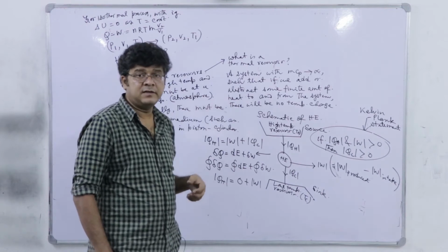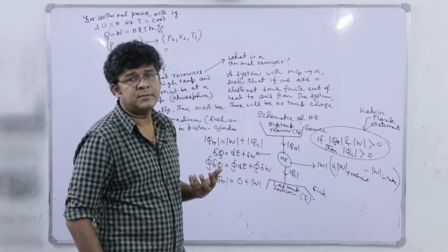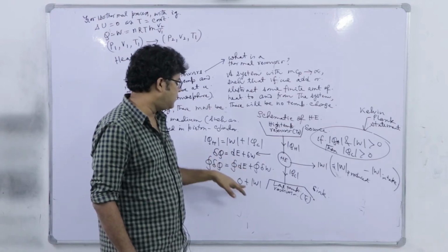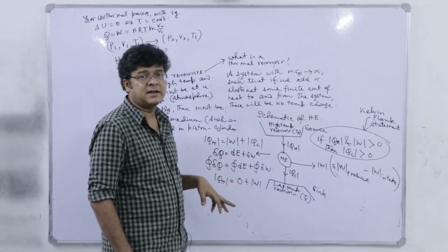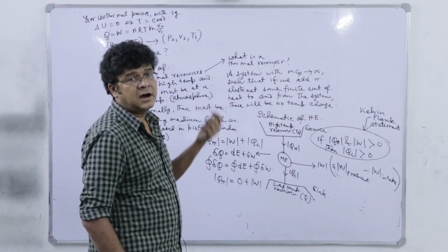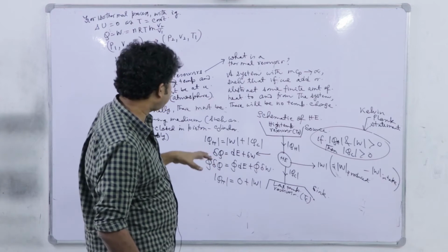However, the energy, which is a combination of kinetic, potential and internal energy, as we have discussed in previous lectures, will be 0 if we perform a cyclic integral on it, because its initial and final states are identical.